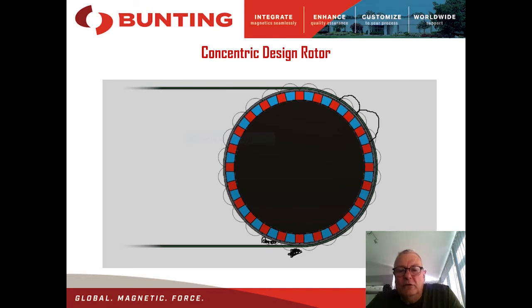So as a rule of thumb, concentric designs tend to be used for larger sized material, in particle size, and also for higher capacities, because we can make this type of design of rotor much wider without having any issues of flex of the rotor at 2000 RPM.